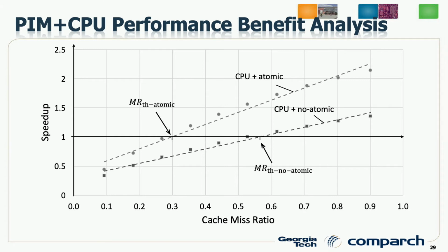But if you offload these atomic operations onto the PIM, we do not need to worry about this parallel memory access effect, because the operations are done in the memory itself, and only one place is changing the data. That means we do not need to worry about multiple compute units changing these locations. So that naturally gives a parallelism effect. When the original operations were atomic operations, and we offload them into the PIM, then we can remove the additional overhead that the CPUs had.